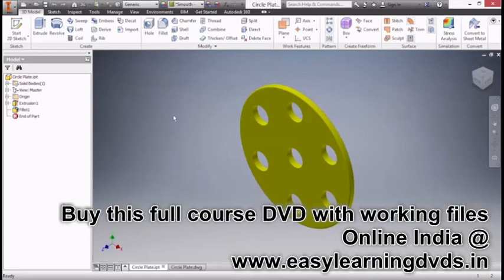In this video, we're going to learn how to create model documentation and understand the concepts around that inside of Autodesk Inventor. So here I have a circle plate IPT and a circle plate DWG from our working files directory. Inside of this IPT file, I can see I have a fully defined model with my extrusion and my fillet. It has all the holes in it, it's sized correctly, but I can't necessarily give this to my shop floor and say, hey, go ahead and make this. I would like to have a 2D documented print to accompany anything I might send off to the shop floor.